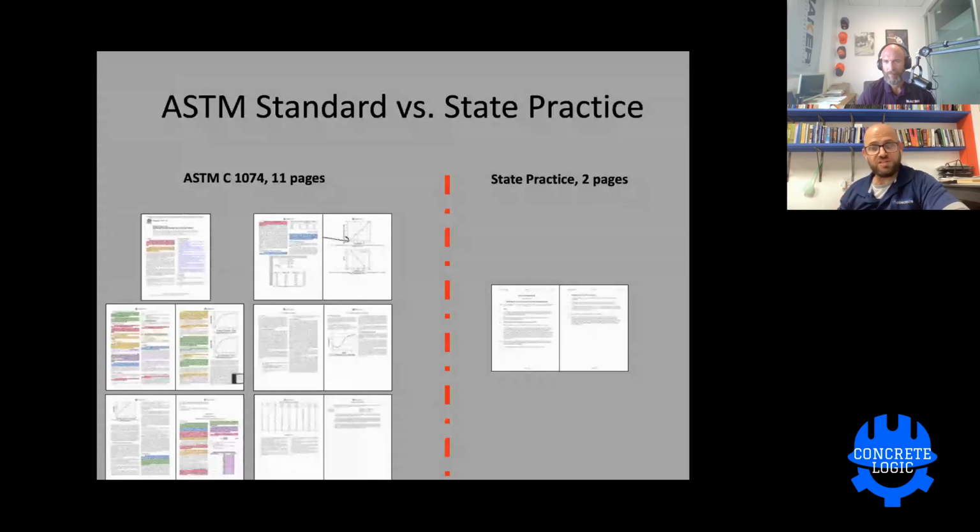And that's really what's happening over a long period of time. You know, you have the 5 stages of cement hydration. You have the mixing phase, which is an enormous spike of heat that we rarely get to see with this piece of equipment. That's within the first few minutes. Then we have this dormancy period, which is where we transport concrete and we put it in the forms and we finish it. And it's anywhere between 2 and 4 hours and sometimes more.